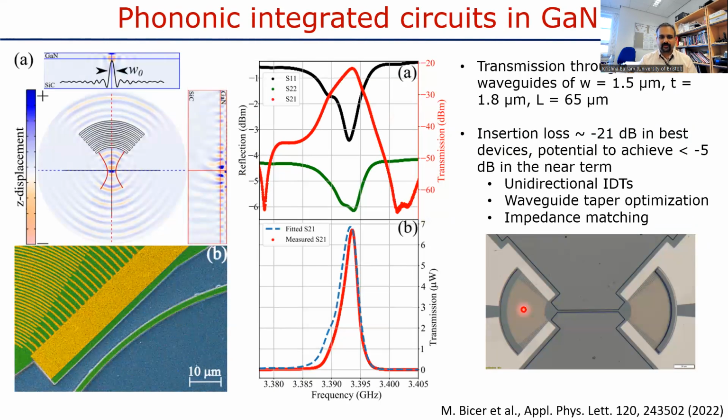And so to begin with, we just wanted to show that you can guide sound inside these structures. So you have focusing IDTs that funnel sound into these waveguides, and you can route sound inside wavelength-scale waveguides on these devices. Now, the key point, and this is something I'll keep coming back to again and again, is that while you can do this and get very nice proof of principle results, the key issue is insertion loss.